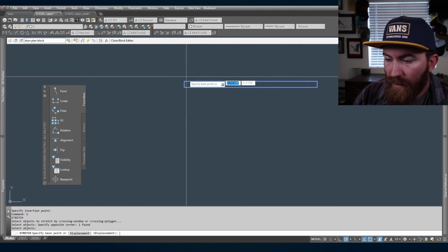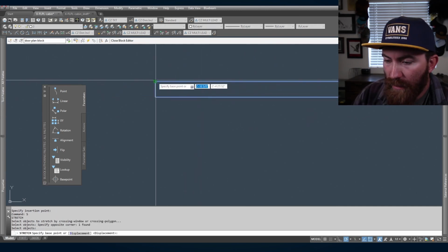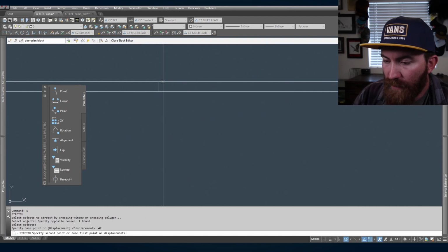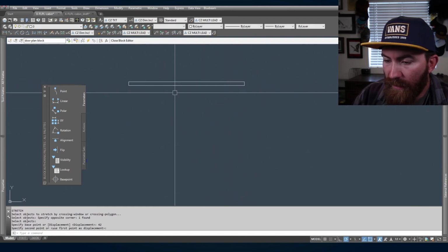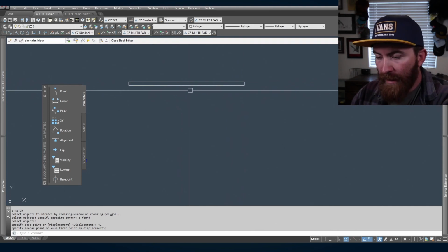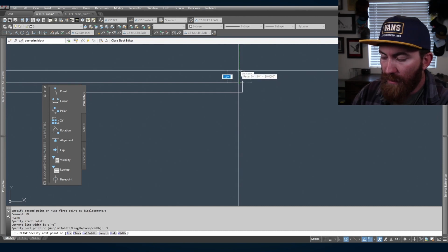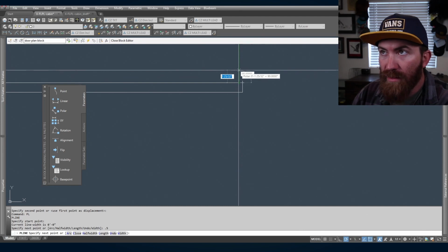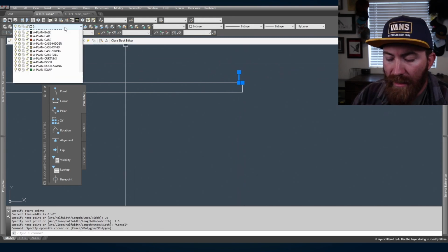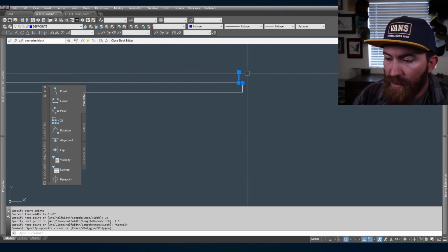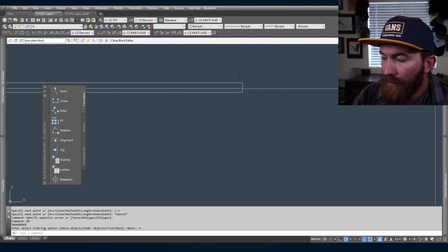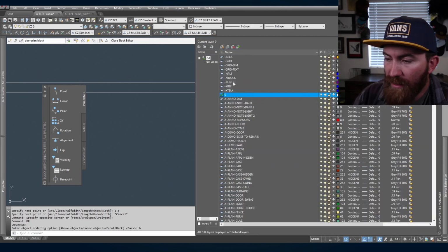I'm gonna stretch from here. I'm gonna say, from there, 42 inches. So boom, we got a 42-inch door, and I want it to park at the finish, and the finish thickness is 0.5. I want it to park about a ½ inch away. Well, actually, it'll probably be more than that because baseboard. So I'm just gonna say 1.5. I'm gonna make that on the def points layer. If you don't have that, you just put that to the back. If you don't have a def points layer, you just come into layer property manager. You type in new layer.